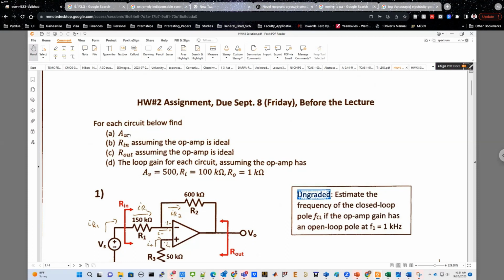Similarly, when you talk about frequency or the bandwidth, the open loop bandwidth will increase by, strictly speaking, 1 plus T naught times, and loosely speaking, T naught times. And that just comes from the formula. Because T naught is generally much, much higher than 1, you can say that 1 plus T naught is almost equal to T naught.